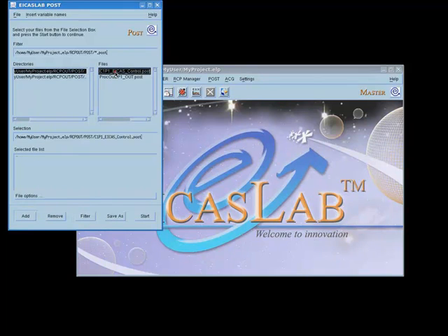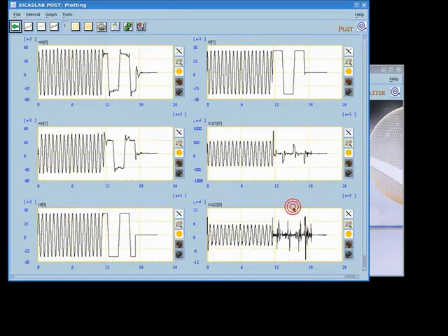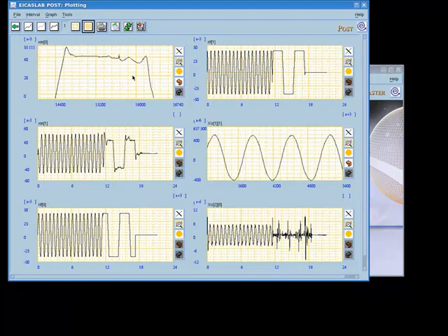Exactly like what was done during the modeling and real-time phases, through the Sim Builder tool the developers can set up EICASLAB for recording on the disk files containing all the variables of interest that allow the overall control tuning. Therefore, during the RCP on-field trial, for each block, a post file is created containing the recorded values of each variable. Once the trial is concluded, the post tool can be used for opening these files and analyzing in detail the temporal trend of the recorded variables.